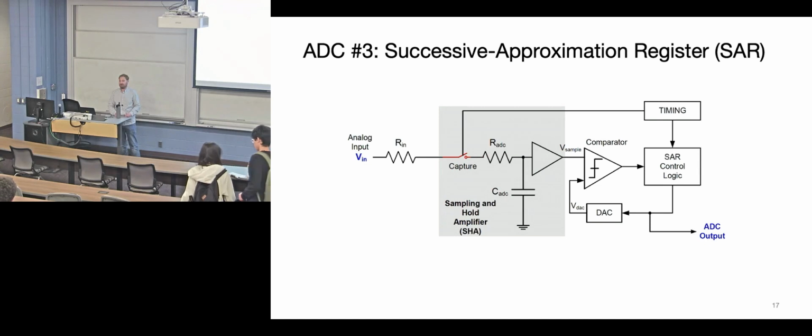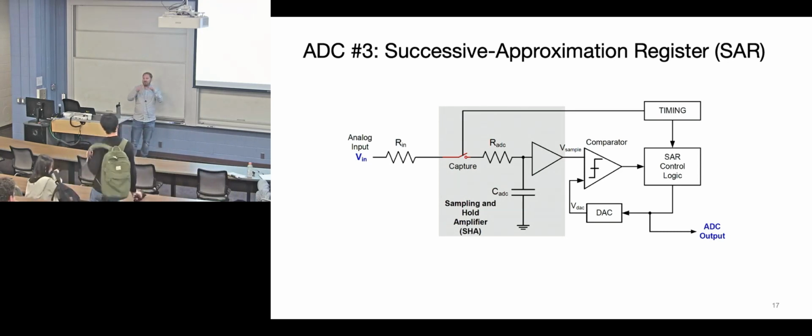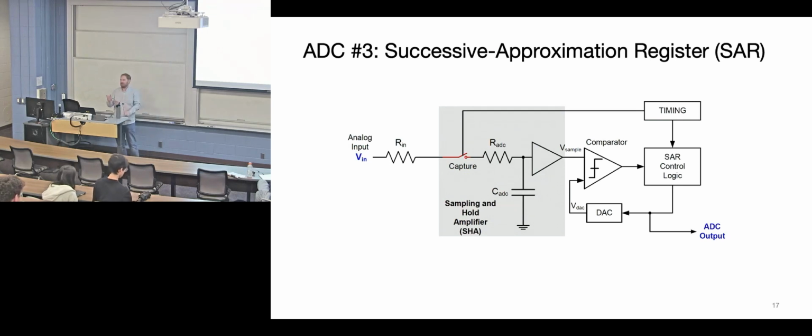You can set the precision up really high. Yep. For very little cost. Yep, you can get the precision high. It really comes down to not your ability to measure time, because you can imagine you can go very, very fast and make lots of little steps in there and get high precision. But it comes down to the quality of your analog things, right? Is there inherent noise? Is your current source accurate enough to give you the measurement? That's what a slope integrator is good for. While the flash is you have to have lots and lots of small resistors. That's the downside. What's the bad thing about slope integrator? Yeah. They're slow, right? That's the trade-off.